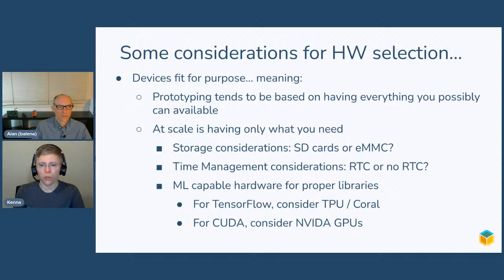We have customers where we say, hey, SD cards are going to wear out over time. And they say, yeah, yeah, yeah. But the cost is so low, it doesn't matter. But then after your entire fleet starts to die and you have 1,000 devices out there and you're replacing SD cards constantly and someone's having to go on site and you're paying for their airfare and their hotel to go on site and replace this thing in the field, the cost of an eMMC suddenly becomes a lot more scalable than the SD cards were. Things like that.